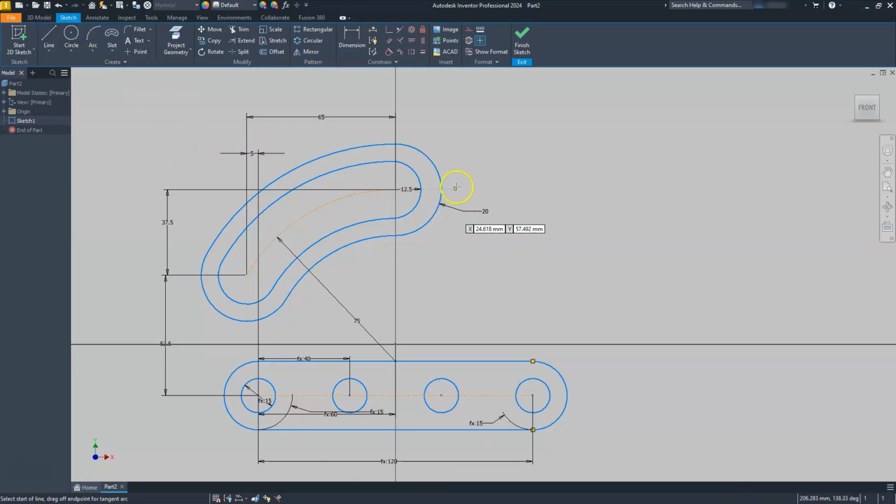Next, let's go ahead and draw a couple of vertical lines here. So I'm going to go a line here. And then I'm going to escape out of that and create one more line here. All right, so what I'm going to do now is I'm going to use that same thing I did before. I'm going to tangent to this one. I'll tangent to this one. Then I'll switch over to coincidence and tell it coincidence to this line here. Coincident that endpoint to this line here. Come to trim. And then I'm just going to start trimming this stuff off. Trim right in between there.